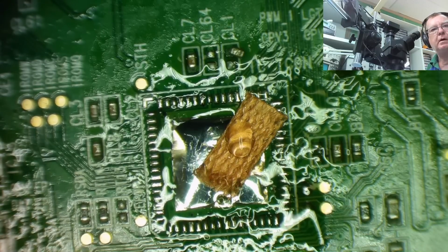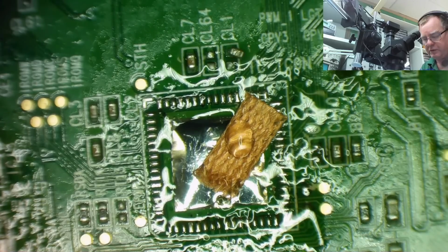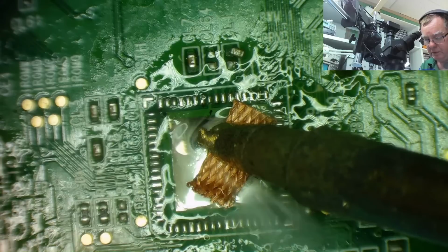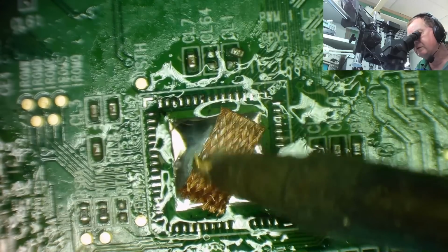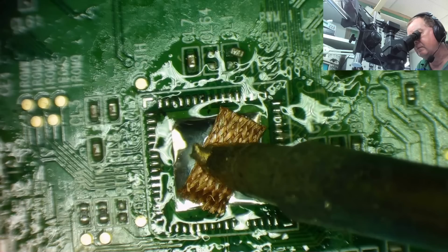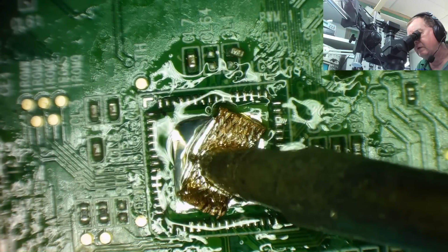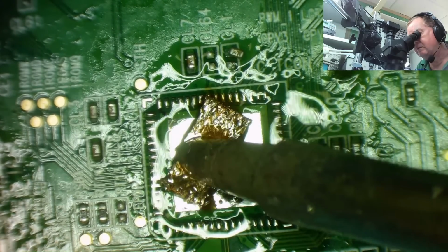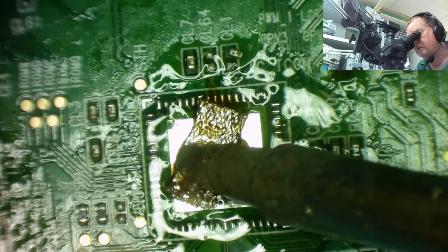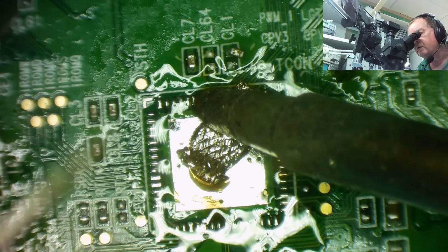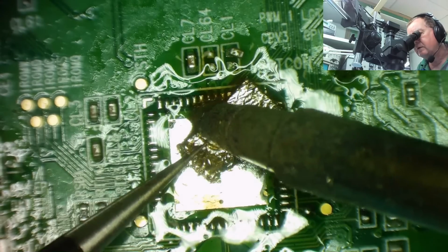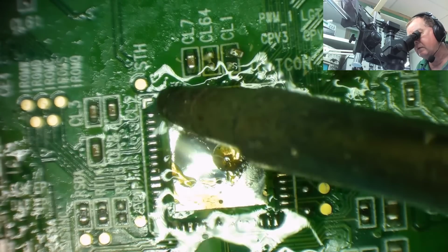Bit of focus. So I may have dislodged another capacitor while I was just getting some good solder onto this thing, but still not a problem. Let's have a look down the microscope and let's just melt the stuff I've got in the middle. I've got quite a lot of solder in the middle of this now, more than I want. Okay, that's good. There's the tweezers. Just keep it hot enough to melt and get it off the board.